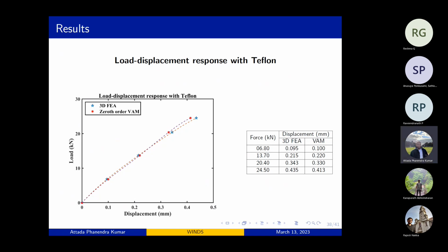This is just the preliminary results. I was working on this for 15-20 days. And when you get that response, do you lose stiffness due to buckling, or is it just a straight linear response? Yeah, it was linear actually, because the 2D stiffness which we are getting is a constant one. Once we go for first order analysis, we can see the nonlinearity coming into place.